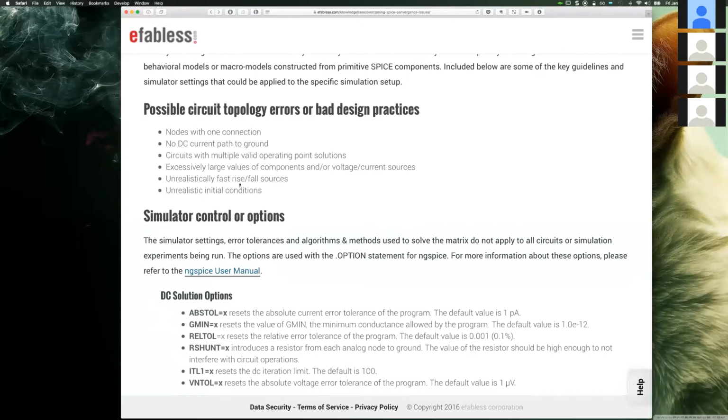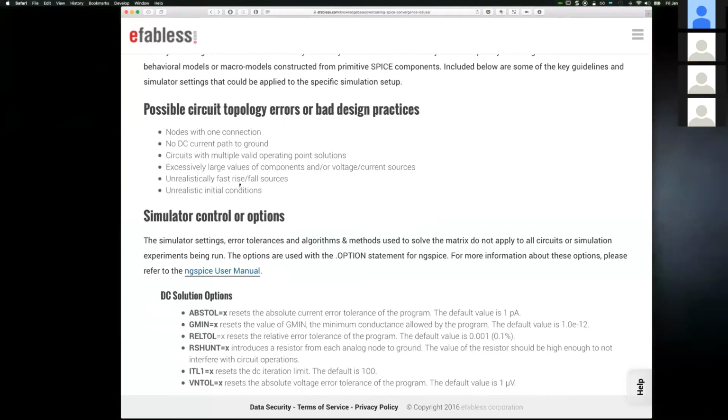an ESD, which is sensitive to basically the rise time of the supply, as if it's an ESD strike. So you will end up with a large current that forces a very steep slope, which requires, depending on that current, if the circuit is operating right, it's not going to happen as an ESD structure. If the circuit is not operating, you will have a convergence problem.